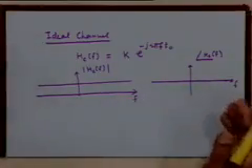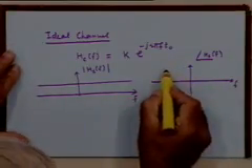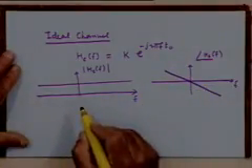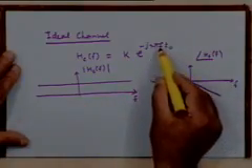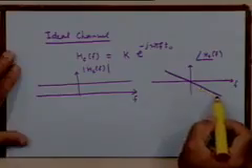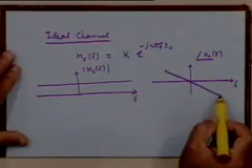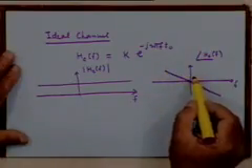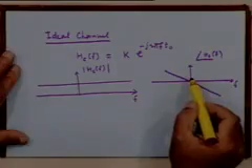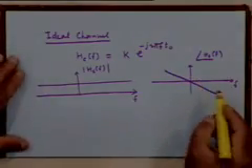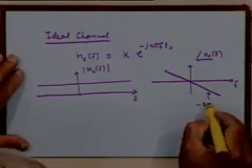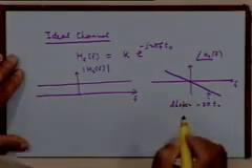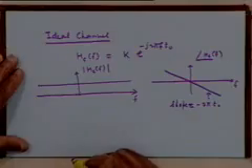What kind of characteristic? It's a straight line, right, with a negative slope, right? The angle is 0 at 0. It's negative for positive frequencies, and positive for negative frequencies, right? And the slope will be equal to minus 2 pi t naught, where t naught is the delay. That's the slope of the straight line, right?